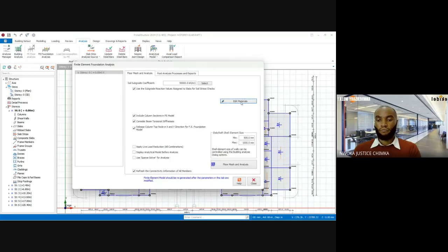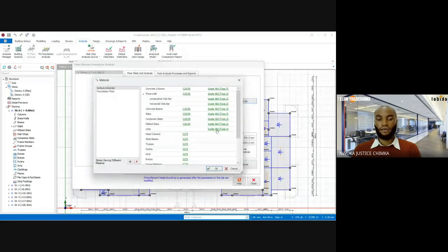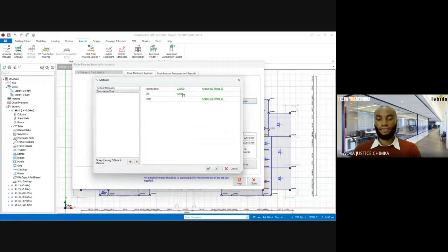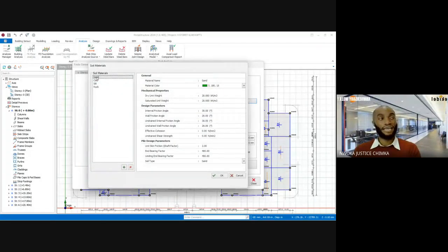Now, back to this other place here. You can see here soil type and all that. If the soil is clay, sand, or silt and all that, it's best to choose that. But knowing that our bearing capacity for this soil is 50, that we assumed yesterday, at that point it is possibly not sand.